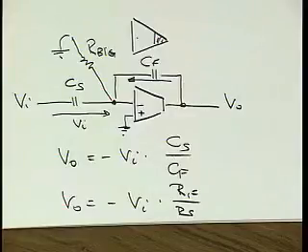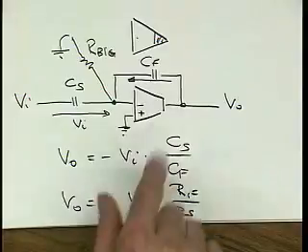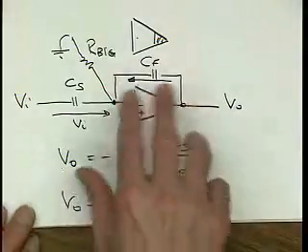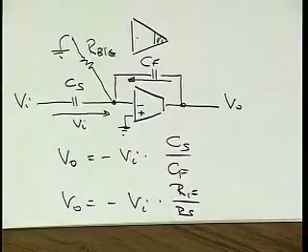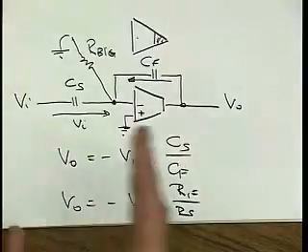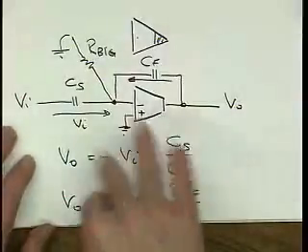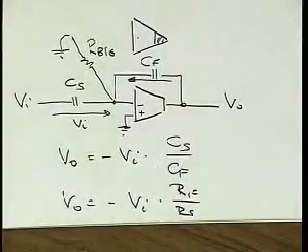In practice, such schemes don't work very well. It turns out that because of leakage and so on, undesired charges regularly accumulate on these capacitors. So we will need to do this at least, let's say, every second, or maybe even a little bit more often than that. And then if we do something like that every second, then every second our signal has some artifact. So in order to avoid these troubles, actual implementations use a clock, let's say the clock rate of the A to D converter that this amplifier is used in, and they just do this reset on every clock. That way you don't have an artifact that occurs in some clock cycles, but not on others. Okay?